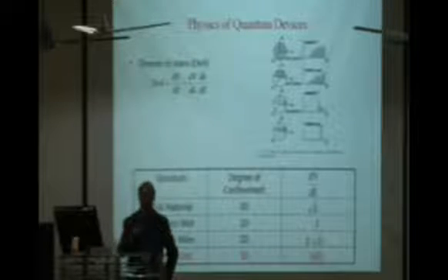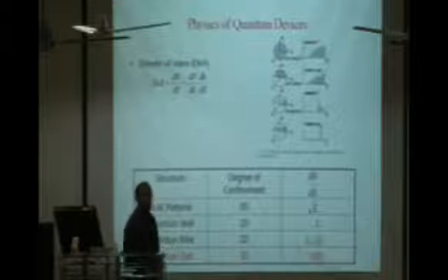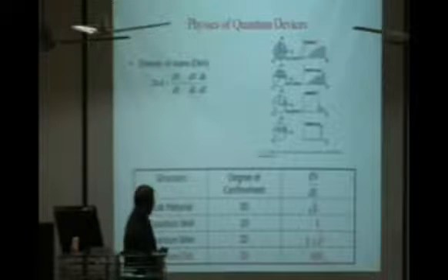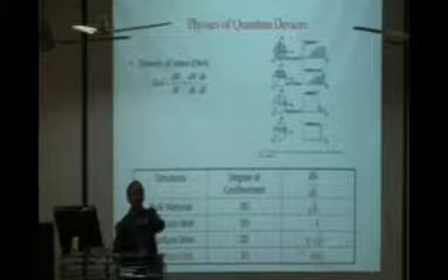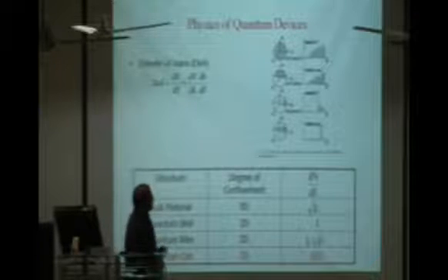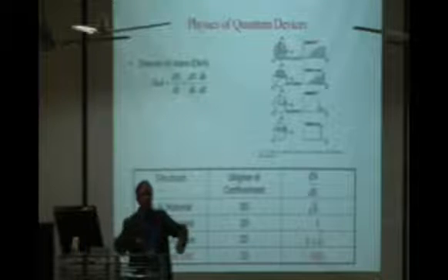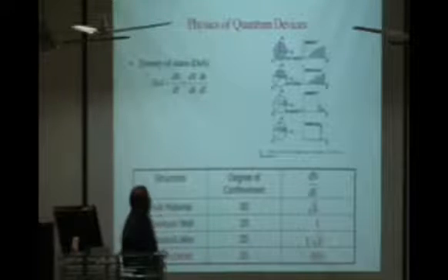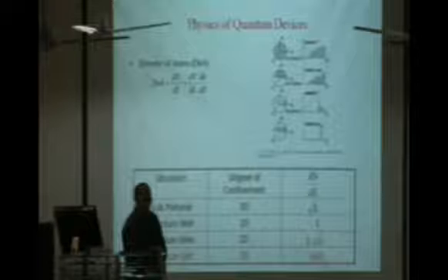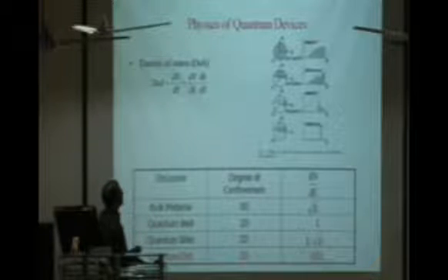Whatever lasers we can get with atomic states, ideally, if you can really make quantum dots with the same monodispersed size and distribution, the density of states is very sharp. But practically it is very hard to make dots in exactly the same size, so there is always broadening here. That is why this is one of the most preferred systems to make these kinds of quantum devices.